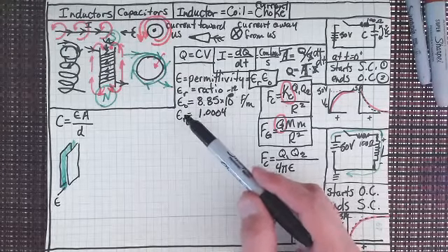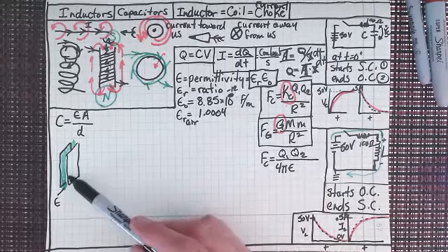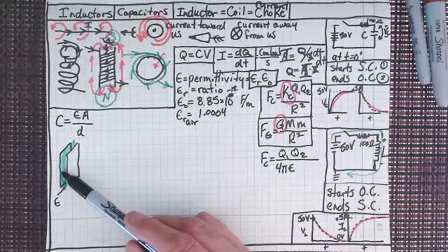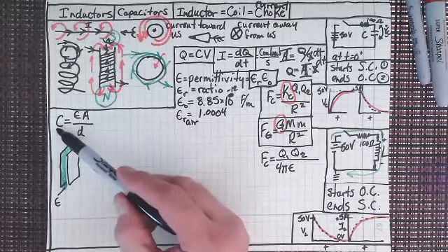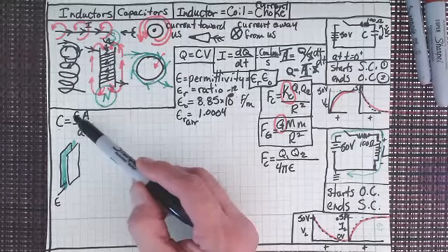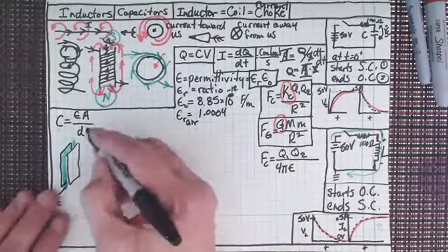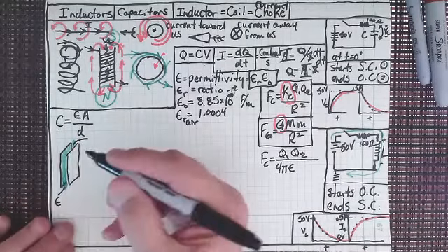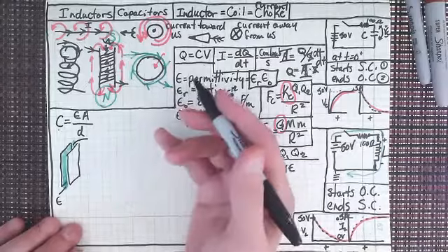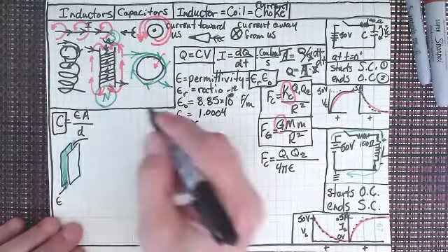High relative permittivity allows much larger electric fields to exist in smaller spaces, right? Look at when we're making a capacitor. Is epsilon in the denominator or is it in the numerator? It's in the numerator, isn't it? So if I could get a dielectric to have a very high permittivity, it's going to make a larger capacitor in a smaller space.